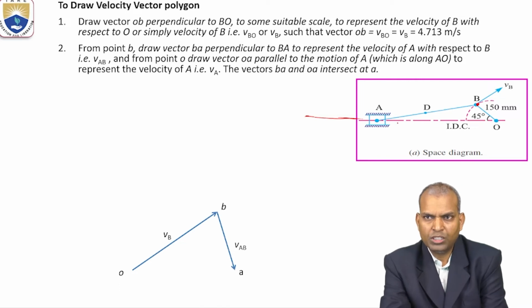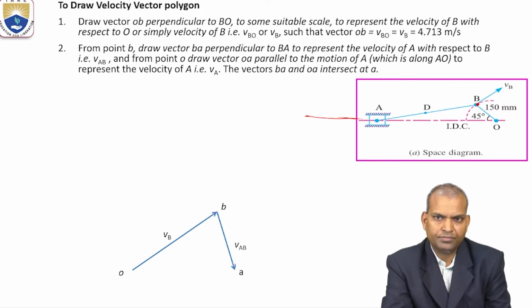Now, on the space diagram, for link AB, keep your minute drafter scale, one of the small scales, and the larger scale indicates the perpendicular line. You draw that perpendicular line, which is perpendicular to link BA. For this link BA, we don't know the magnitude, only the direction.